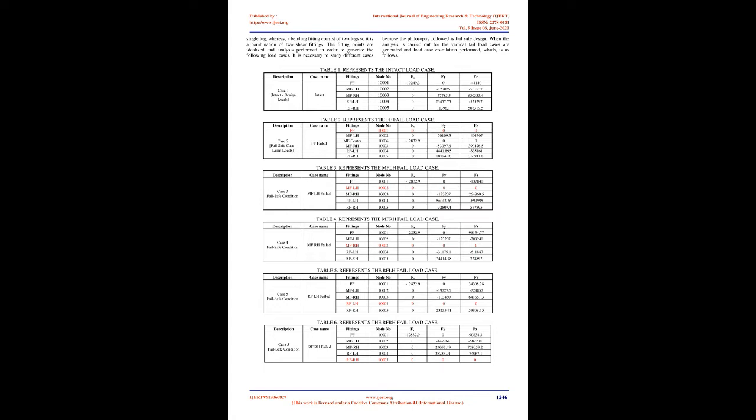If we went with a configuration of 2 shear fittings and only 1 bending fitting, then in case of failure of one of the shear fittings, the load in the y direction, which has a predominant effect and creates large bending force, will not be diffused completely and would ultimately lead to the failure of the entire vertical tail. A shear fitting, though it transfers shear loads, is critical due to axial loading. In this study, the fail-safe design philosophy is adopted.